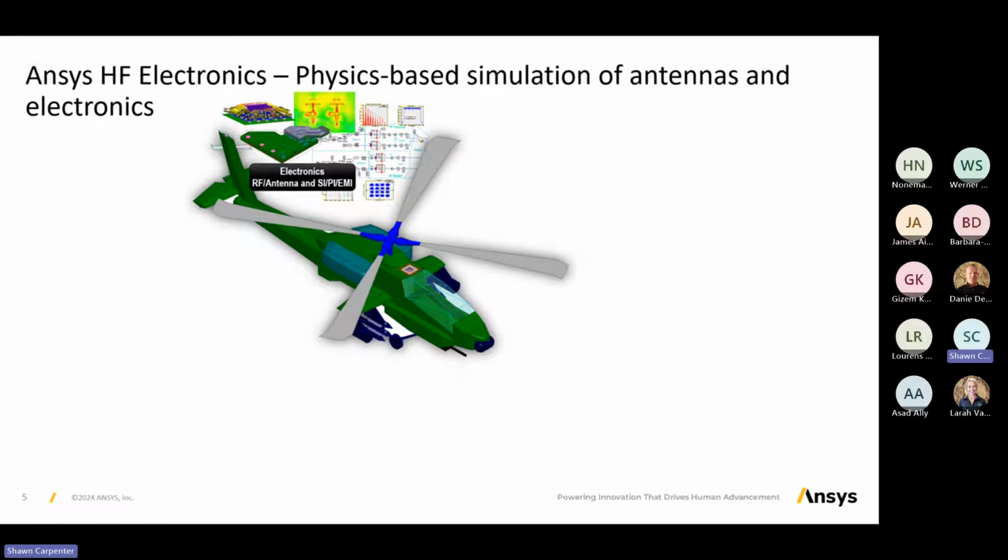So you may have interposers, you may have package interconnects, you may have wire bonds, you have a very complex package, potting structure. That package sits on a board. You want to model the interconnects to the board. The board may have emissions, may have crosstalk. We need to be able to capture and model these things in a way that we can relate then to our functional systems designs. And we do this with brute force electromagnetic simulation at speeds that you would be quite surprised at.